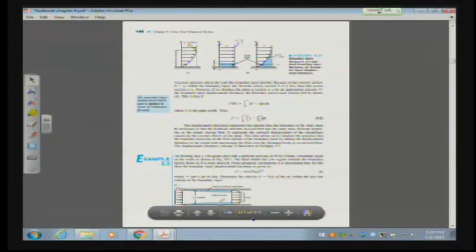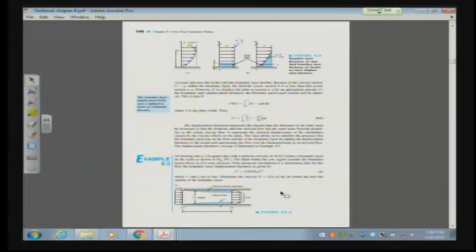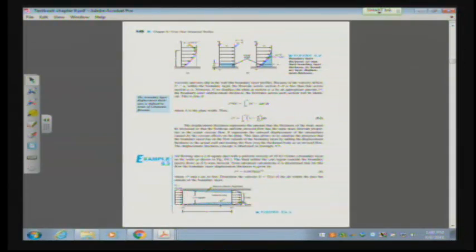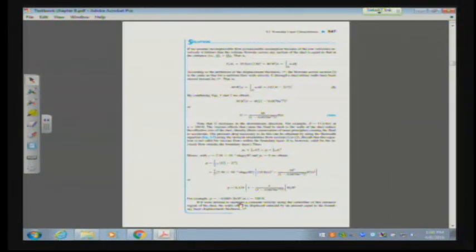So on the outlet of this conduit, we have a sharply defined, it's not really parabolic, but you can sort of see just by the function of the velocity that we have a viscous region where we have a cling here at the end, where we have that no slip condition, and we build up rather quickly to some average velocity which remains basically constant in that core of inviscid flow.